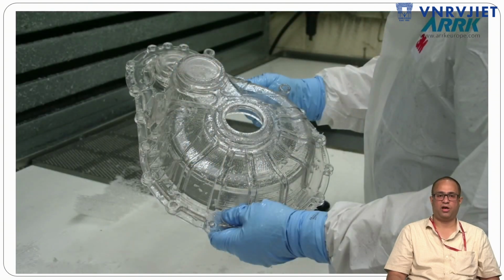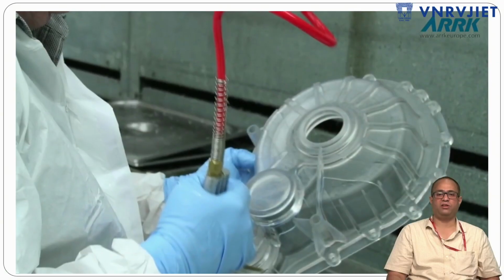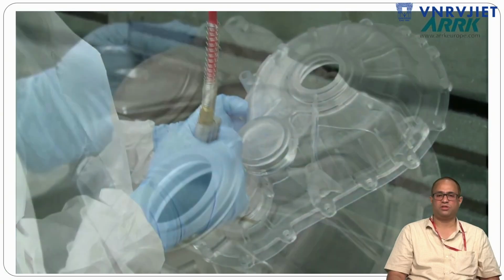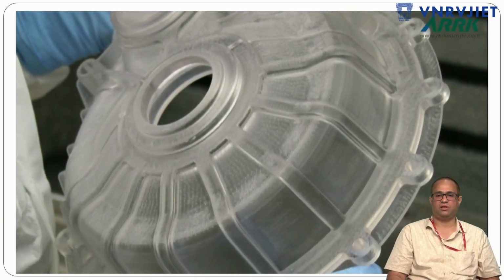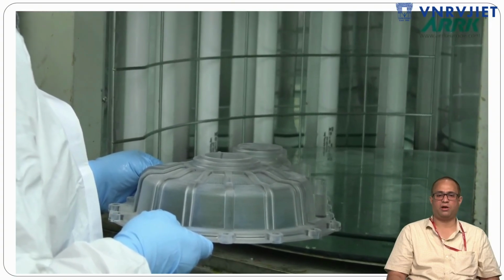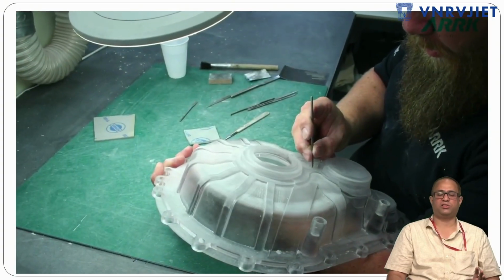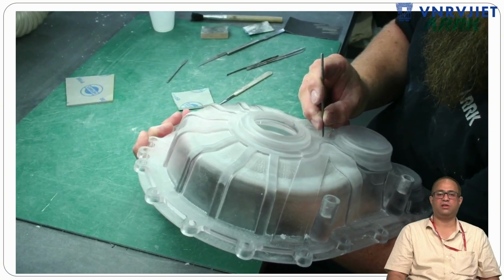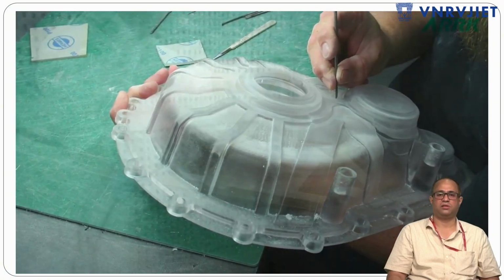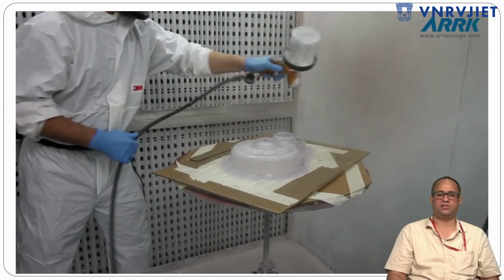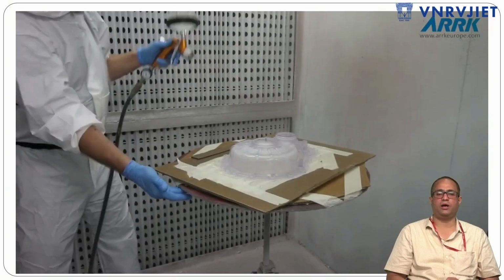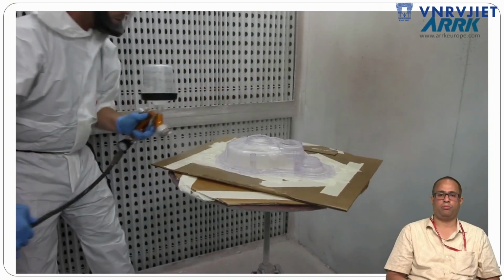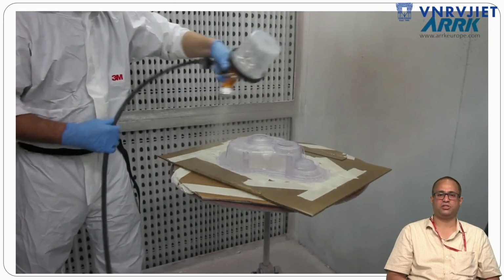You can see after removing the supports, the complex profiles and then additional post processing. You can see the accuracy of the part, and the finish of the part. SLA is going to produce a great amount of accuracy for all the parts. As you can see here, this is additional post processing: priming and painting to make the surface a shiny finish.